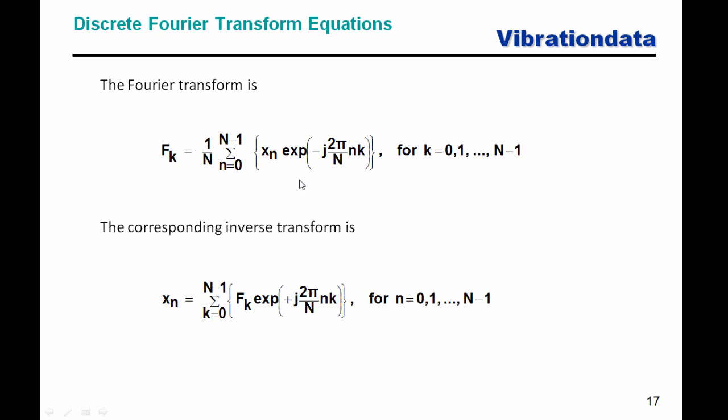There's another advantage to doing it this way. We're no longer integrating with respect to time, so we don't have a delta t here, but instead we divide by the total number of points N. In some sense, we're taking a weighted average of the time domain for each inner loop, and we do this for each frequency of interest. Another great thing is, let's say we have acceleration in g as our time domain input signal. Our Fourier transform will now have units of acceleration in g, and that is welcome news for us as engineers.